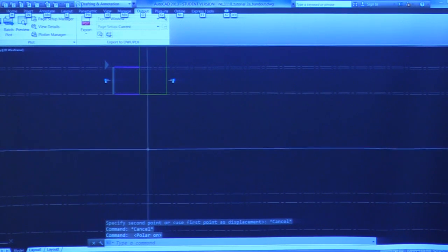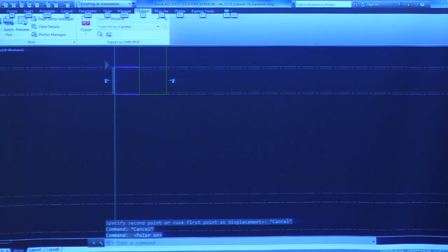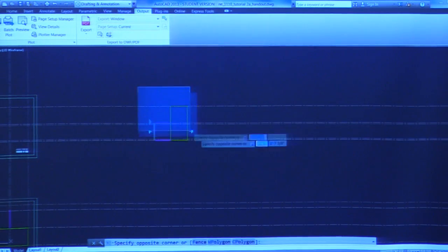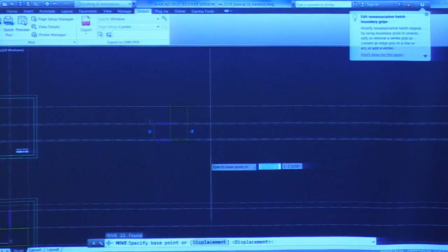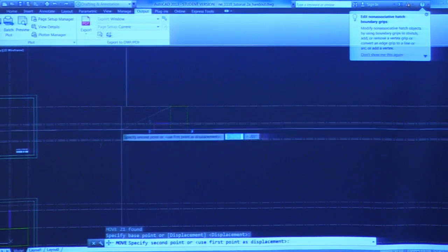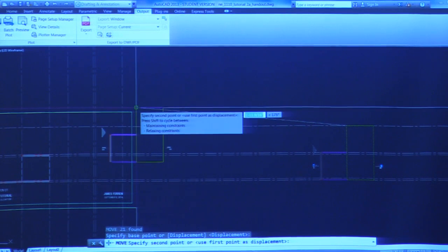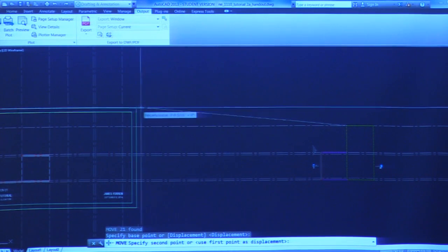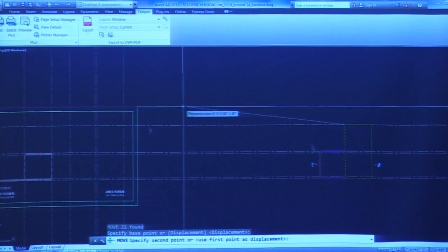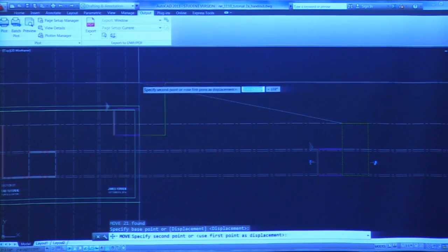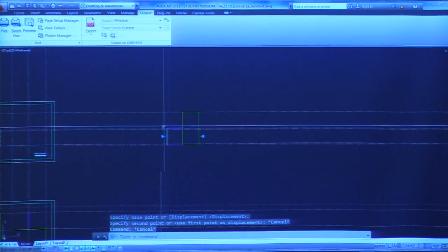Another helpful snap that I'm just going to cover right now is, if I go down here, object snap tracking. What that lets me do, you'll see come in handy later. If I want to move something in alignment with a different line, I can touch that line. AutoCAD knows that I'm trying to snap to it or line up with it. You see a little green line trailing off, staying horizontal with it. So it's a nice automatic alignment with other objects.